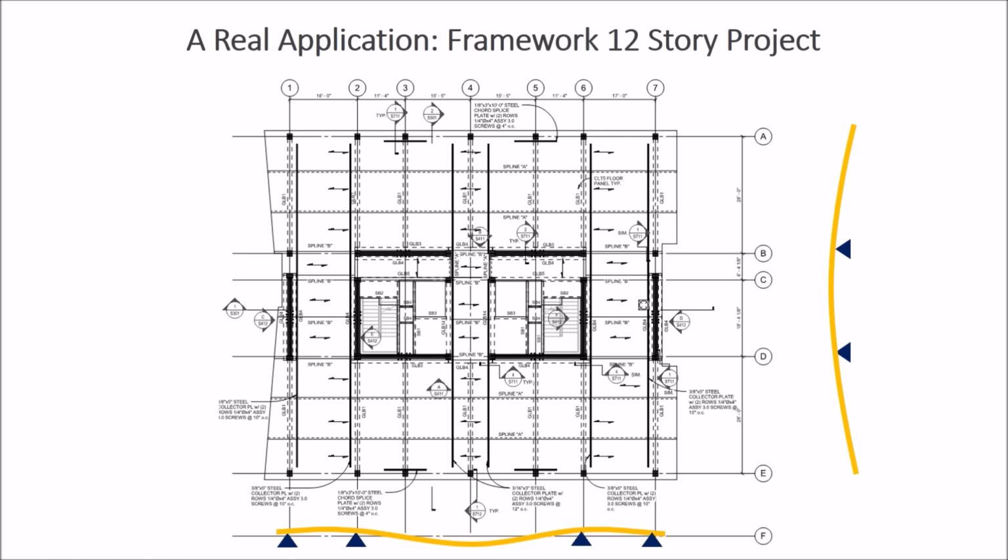Another objective of the KPFF Framework project is not just to have a low damage vertical force resisting system, which is the rocking walls, but really to have a low damage system across the board. So we designed the diaphragms to a design load that was well above the minimum design load for diaphragms that you find in ASCE 7-10. And we have 2 holes in the middle, so that complicates the behavior, but that's not atypical of an office layout.